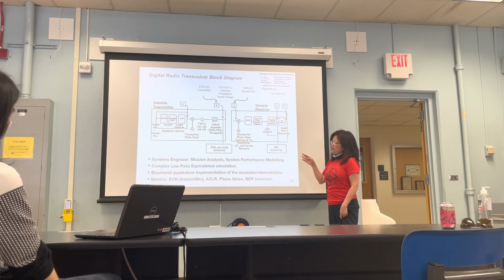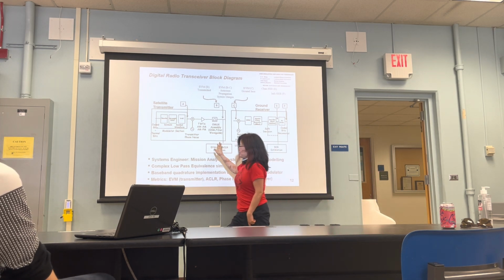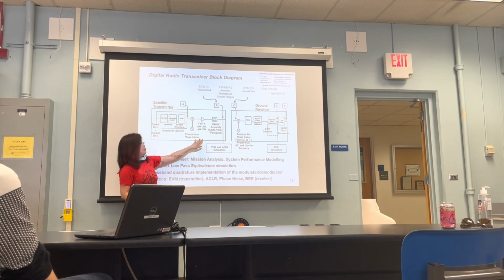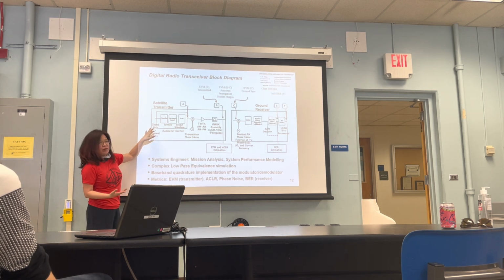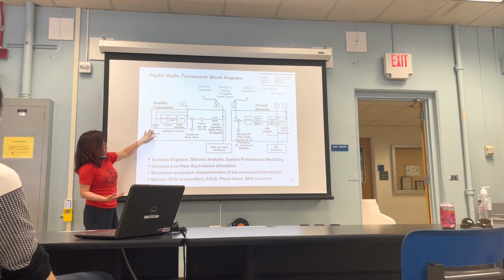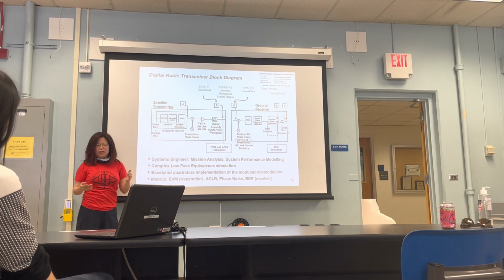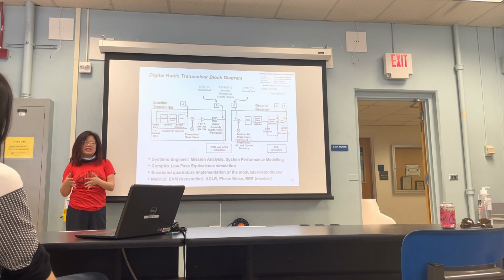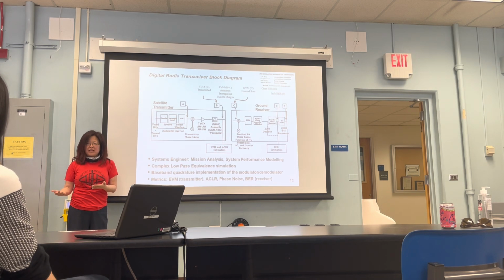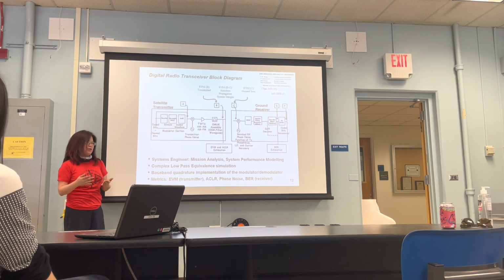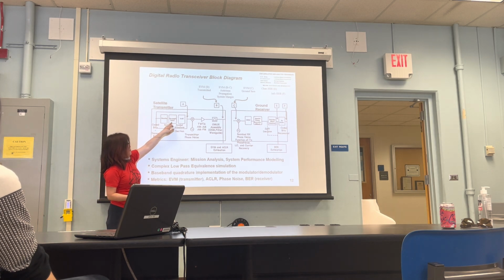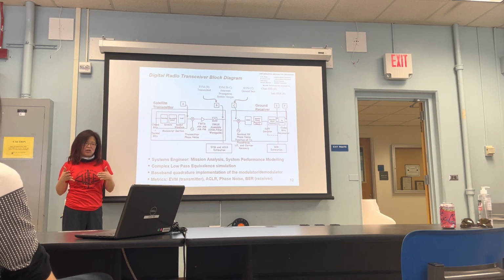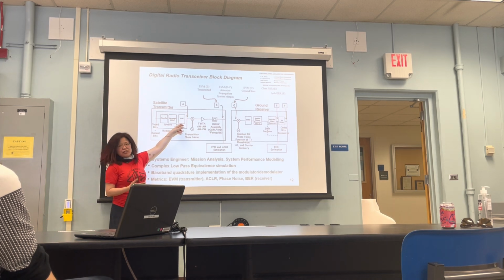So this is the model of the transmitter. Everything here, this part is the transmitter. Very quickly, the way you model it, that I modeled for Washington, D.C., is the coding, which is the forward error correction, not shown here. Then the encoding is how you go from bits and n-tuples to a symbol. For example, if you've taken Professor Morales' class, then you know you can get BPSK, QAM, that's this encoding. Then you upsample and you perform the Nyquist root raised cosine on the transmit side, and then the digital to analog converter.